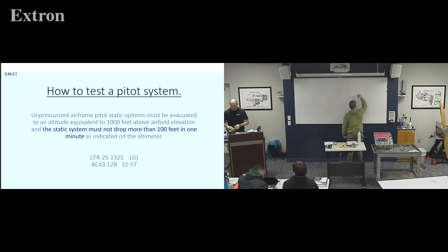Would there be any occasion that you switch it around in flight, like, okay, now you want to see your pressure, now you want to see your... Yeah, so if I need to correct my airspeed indicator, not even correct, but just set it correctly, that's one where you would wanna check your pressure altitude. And that's where I was saying, let's say ATIS says we're set at 29.73, and I've got it set in my little Kollsman window, and I go, okay, I wanna set my airspeed correct.